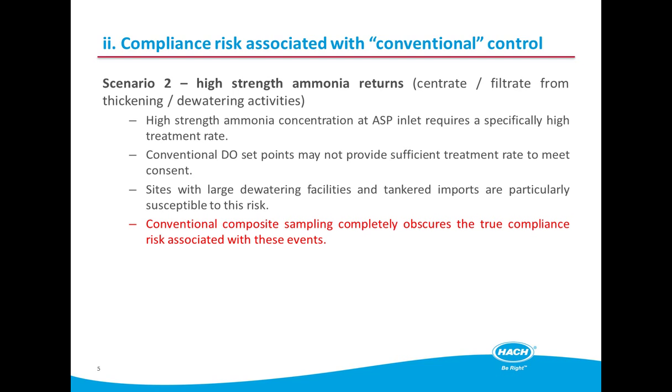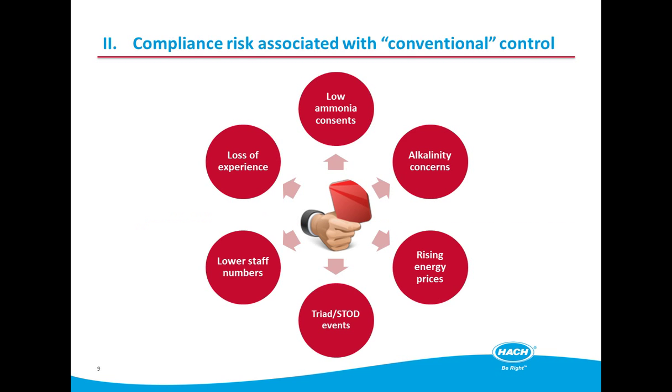And just to re-stress the point, composite samples will not accurately reflect the true compliance risk associated with these returns. Only online analyzers provide the true picture when considering compliance risk in all operational conditions. This slide is simply to show that there are further increasing pressures on the wastewater treatment works compliance. So the compliance pressures will only become more challenging in the future.